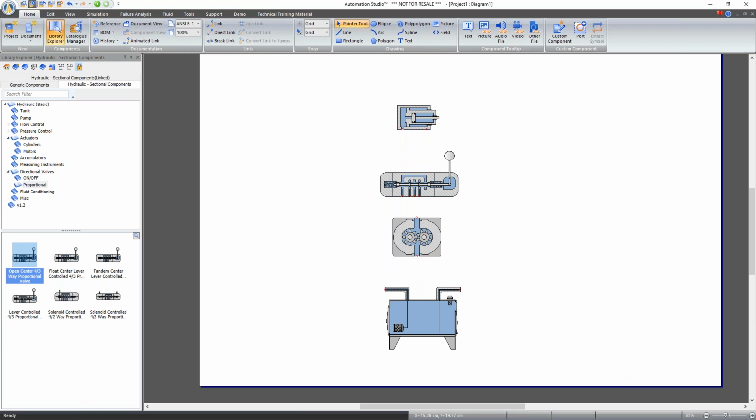So you have on the inlet of this pump, from the pump to the P port of my valve, from the A port to my cylinder, from my B port once again to the valve, and I bring this tank port to the other side. Once again, you can make things a bit cleaner to see where I can use that and so on.